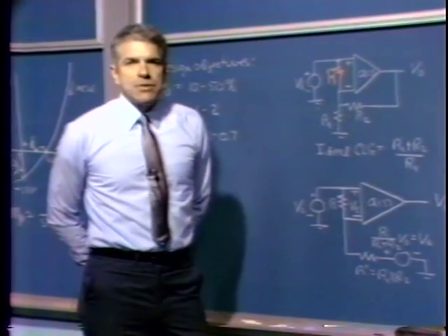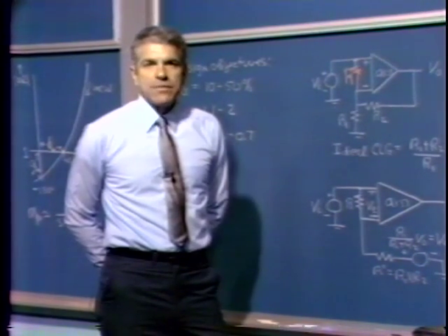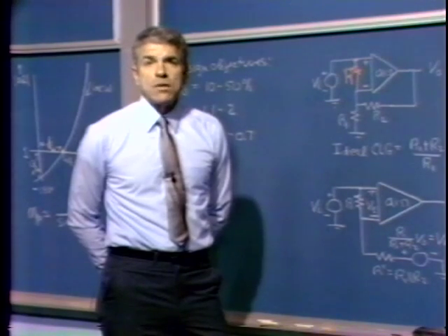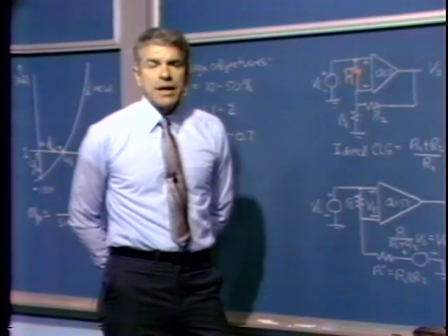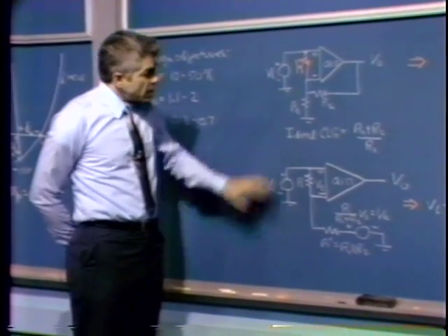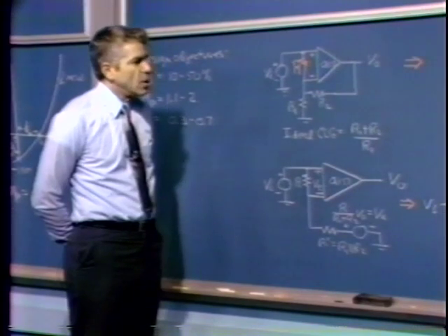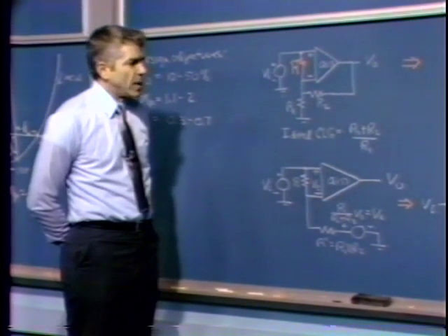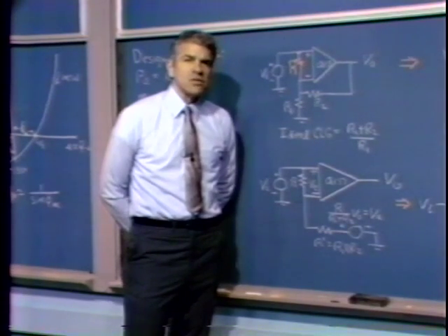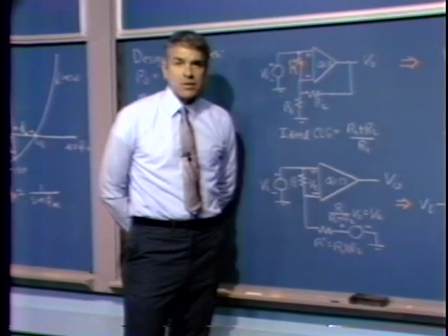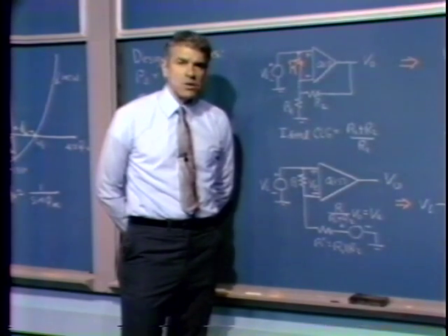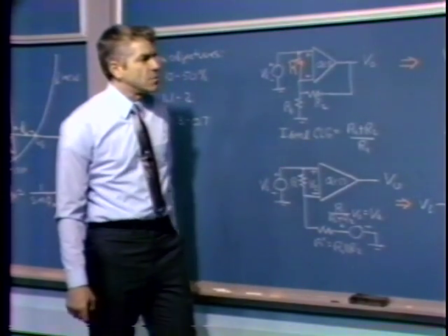Well, suppose we'd like to take such an amplifier and run it at a closed-loop non-inverting gain of 2, for example, but the manufacturer only guarantees stability if F is less than 1/5. In other words, if we attenuate the signals fed back by a factor of more than 5. We can use this sort of approach in order to attenuate the feedback, the signal fed back to the amplifier, lower the loop transmission magnitude so that the amplifier configuration becomes stable. As I say, there are commercially available amplifiers that are intended to run that way. You gain certain advantages in the design of the amplifier if you design it other than for stability with direct feedback. And when that happens, if you want to run the amplifier at low closed-loop gains, this sort of approach allows you to maintain stability.